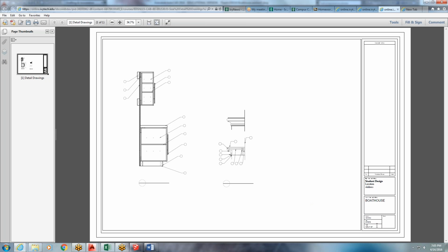inches. Write that down in your notes unless you want to have to watch the whole video because you can't remember that it was at 7:05 p.m. So go ahead and just write 1.5 inches equals 1 foot 0 inches. That's different than the 1/4 inch scale of the rest of our drawings. Details are always bigger, and this is a pretty standard size for details to be drawn at. So now when we print on that big piece of paper, that teeny tiny text that you saw in the drawing is actually blown up quite a bit and easy enough to read.